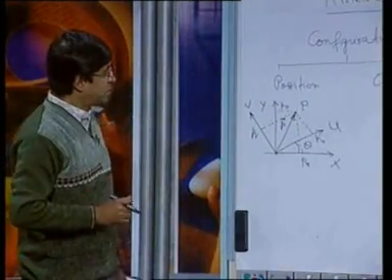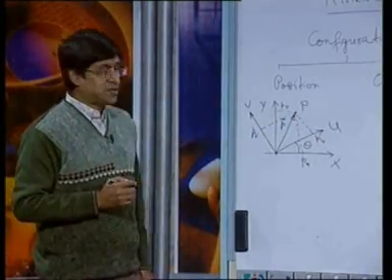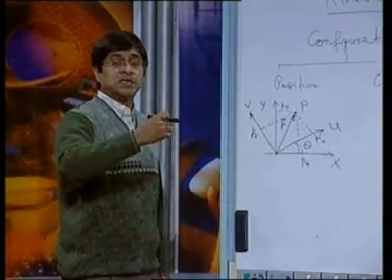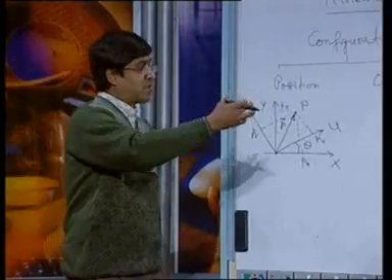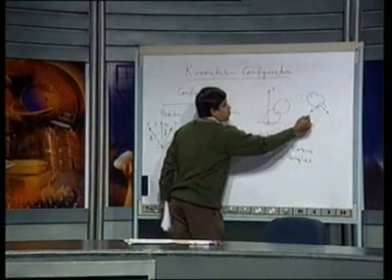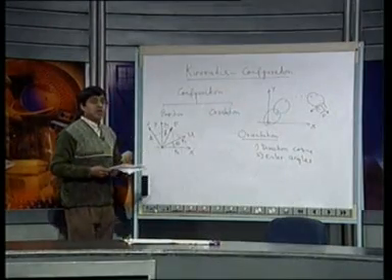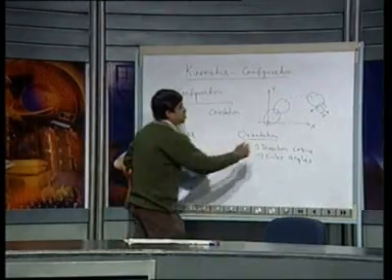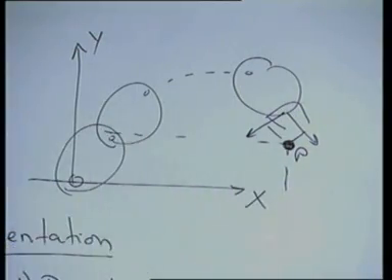Now, what we want to do is, knowing the values of P u and P v, calculate P x and P y. Now, why is it required? Say for a robotic application, I know the coordinates of a point P in the end effector frame, at the end here. Since all the control is done with respect to the fixed coordinate frame, I need to know its values with respect to the fixed frame.